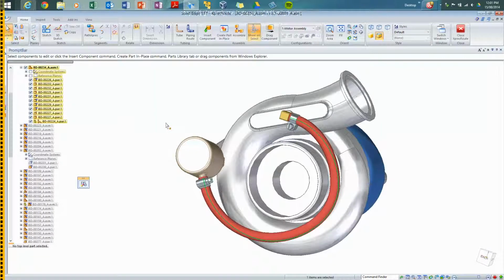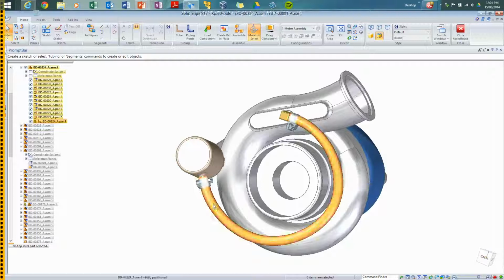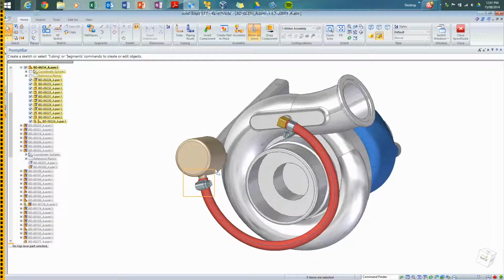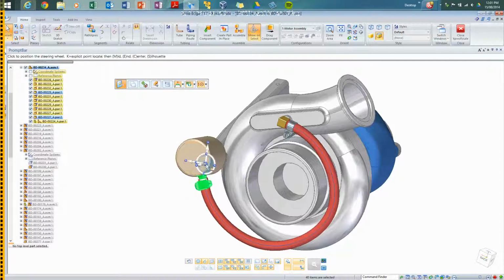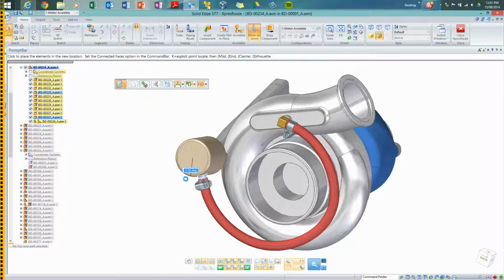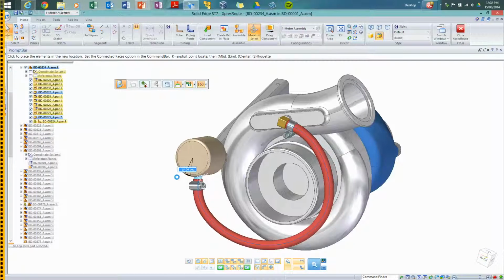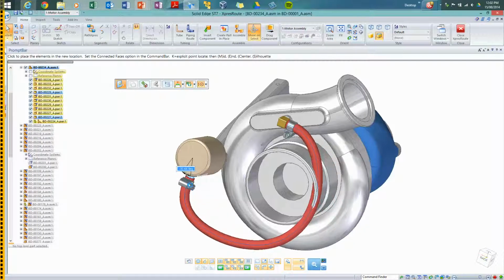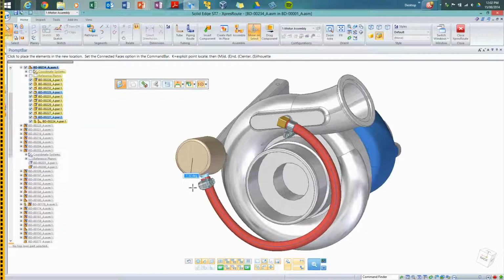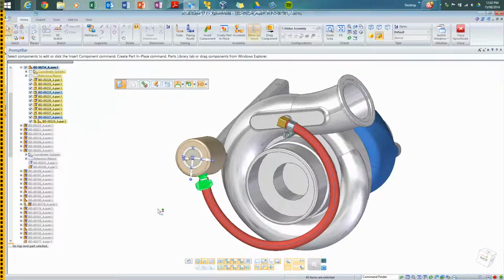And what we'll do actually, if I use Control U, I can do an update links, and you can see the tubes updated. And if we change the view slightly so that I can fence select the bits that I need to change on these couple of synchronous parts in this assembly, if I then rotate this around, I could have done this edit earlier on, but I didn't. But you can see now that actually the whole tube is moving. That 380mm length is being maintained. If I performed this edit before I did that, then it would just be making this tube longer. There'd be no control over the length of the tube at all.